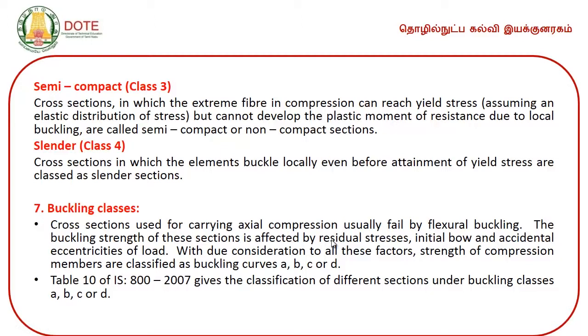being thin elements, probably the topmost flange corner will cool down first, before the middle portion cools down. So these types of unbalanced heat exchanges between the material parts are the reason for the residual stresses. In simple words, residual stresses are the stresses which remain in the member after its manufacturing.